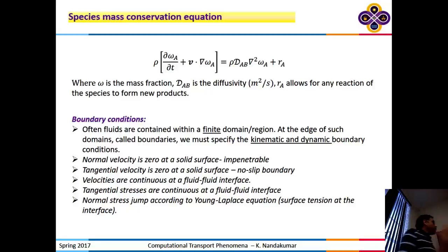But as I said, for polymeric fluids, if you have a CMC solution or polyethylene melt, when you're pumping these through, one end of the molecule can stick to the wall, the other end may be freely floating inside. So it encounters something called a stick-slip phenomenon. Polymer solutions typically exhibit that, and those do not obey this kind of a linear relationship with beta equal to infinity, for example. So the way you isolate the system and come up with a reasonable set of boundary conditions is based on our intuitive expectation that needs to be validated against experiment. A very good question.